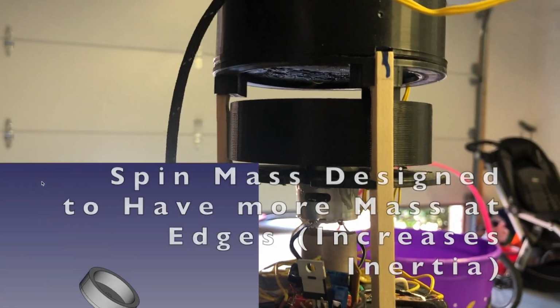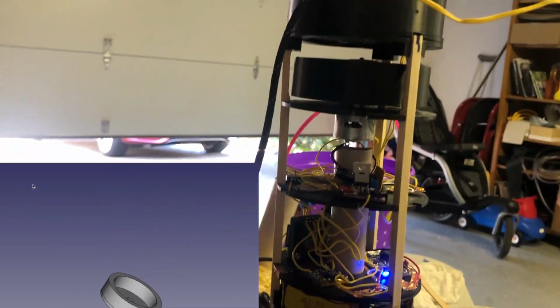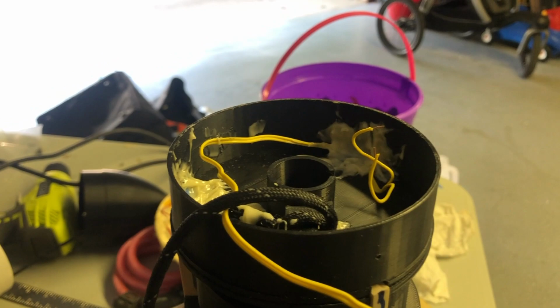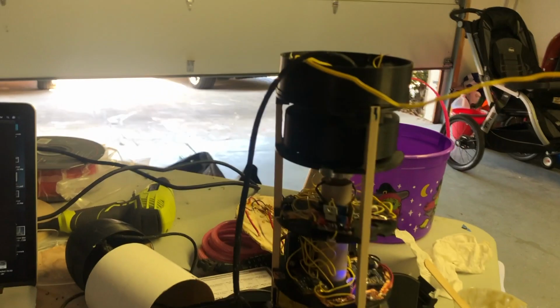I'll show you in the CAD that I try to put as much mass as I can towards the edges. And I try to make this thing as low as possible. This is as physically low as I could go. And then up here I have a charge for the black powder ejection charge, and also the string that this thing will be hanging from. So this will be encapsulated in here, which goes on there and then screws in, and then we'll call the nose cone we made, which is tied in. So I have a video where I blow it off as well.